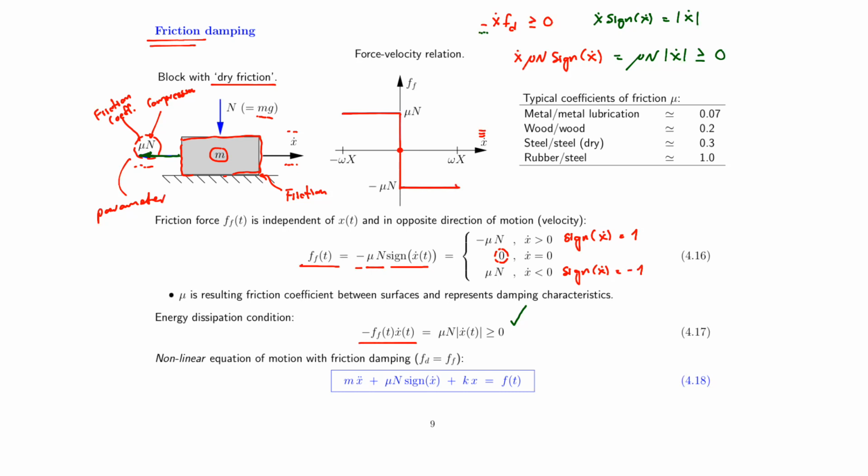And we can even substitute our friction force into the left hand side of our equation of motion, where you will see that we now have a highly nonlinear term inside our equation of motion, representing the switching between positive and negative friction force, with immediate switching associated with velocity equal to 0.